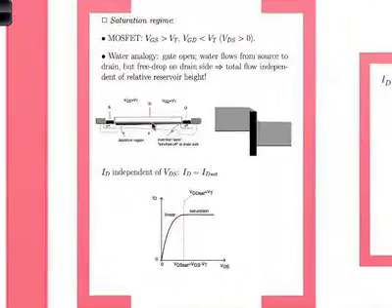The third regime is the typical operation for amplification, the saturation. In this case, the gate to source voltage is greater than some threshold, and the gate to drain voltage is now less than some threshold, and the drain to source voltage is greater than 0. What does this mean? This means that the gate is open. From the water analogy, this gate is open. The water flows from the source to the drain, as shown here.